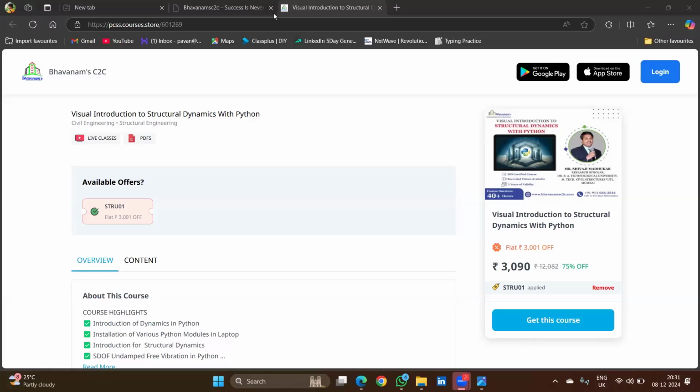So you can write in Python and you can get it in CAD. Like in my office, we have a standardized set of layers created in a Python file, and I get those same layers in my CAD. So I don't need to do new layer, new layer, new layer every time. I'll write a script and run it. CAD will have the same layers.